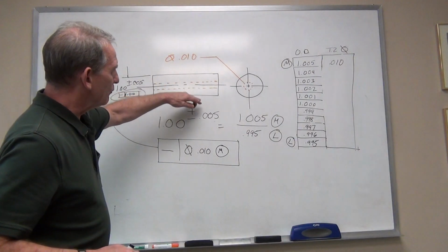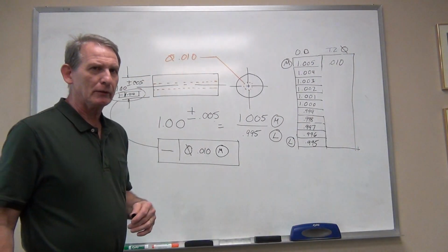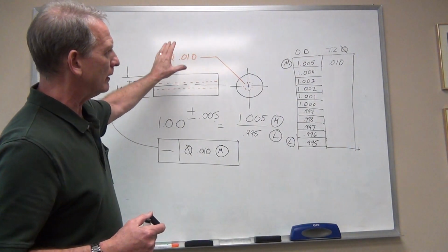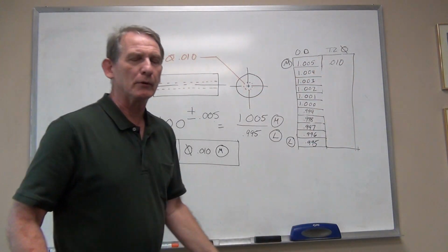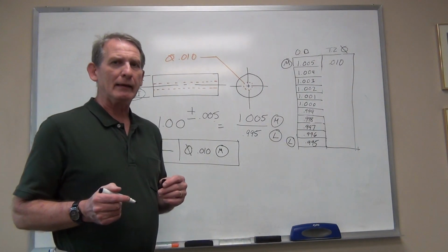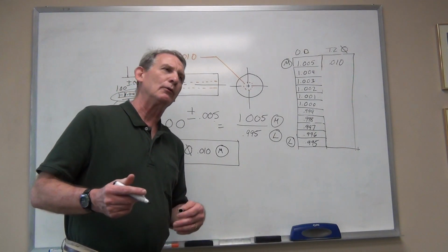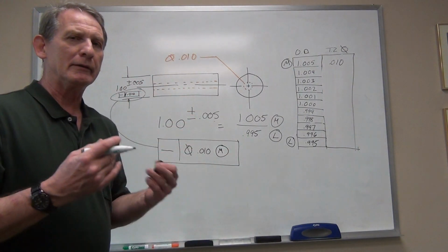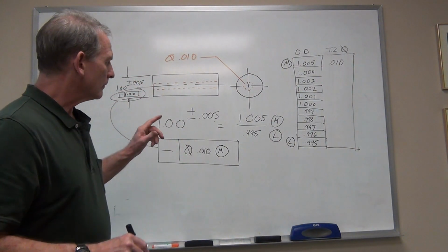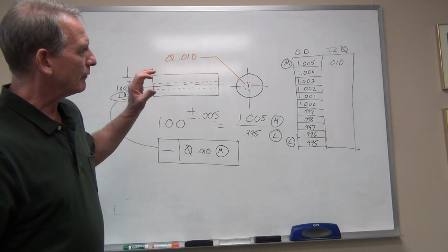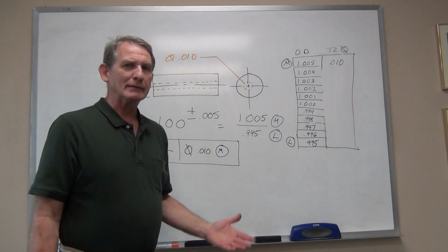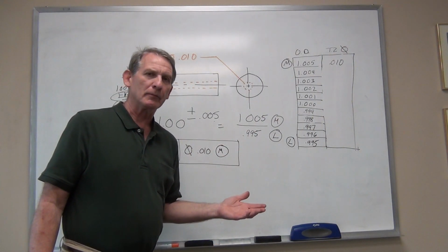Let's say the first shaft you hit right at maximum material condition. It measures 1 inch 5 thousandths. You have to check the straightness. You get a 10 thousandths diameter straightness tolerance zone. The next shaft that you make is a thousandth smaller. You say, well, I don't want to be right up there at the limit. I'm going to dial it down a little bit, take an extra thousandth off, so my second shaft measures 1 inch 4 thousandths. So it is a thousandth smaller in diameter.